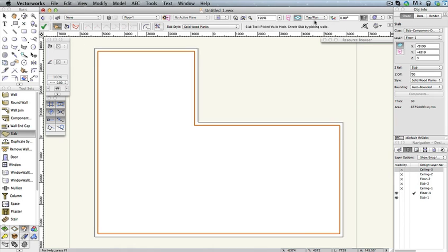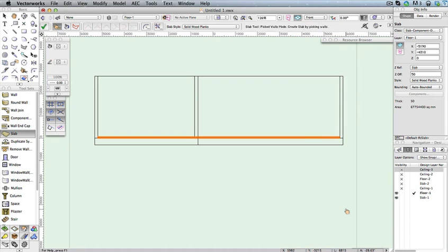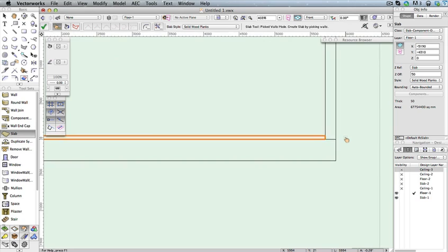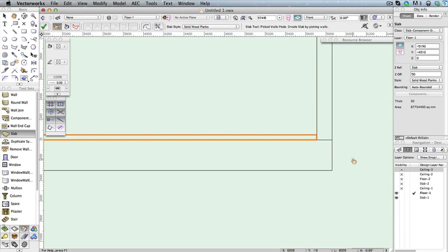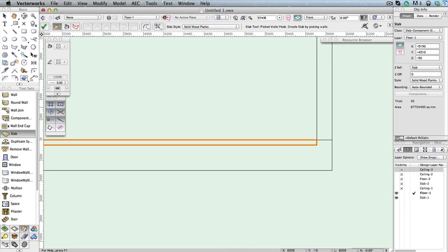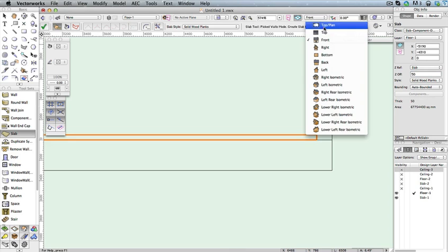In the view bar, switch to a front view and zoom in to the bottom right corner of the model. Here, you can see the top face of the floor is offset 50 mm above the slab layer. If we had left the Z offset field at 0, then the floor would have been beneath the slab. OK, return to a top plan view.